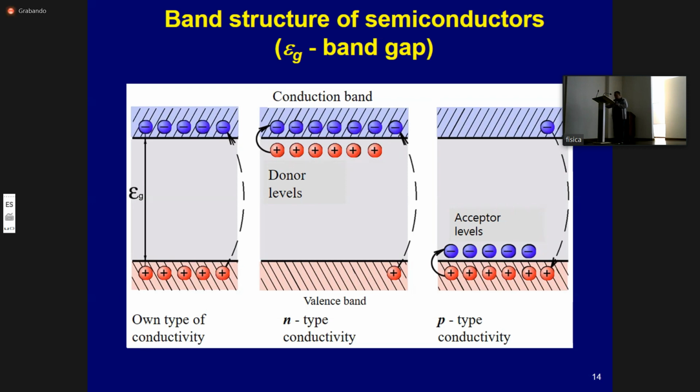The switching circuit of a semiconductor detector with the p-n junction is shown on the slide. Here layers p and n are separated by a transition region in which charge carriers are created under the action of ionizing radiation. These newly formed charge carriers are carried away by the electric field to the electrodes in a fraction of a microsecond. Silicon and germanium are the most convenient materials for semiconductor detectors with a junction.